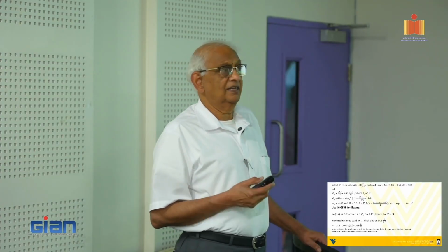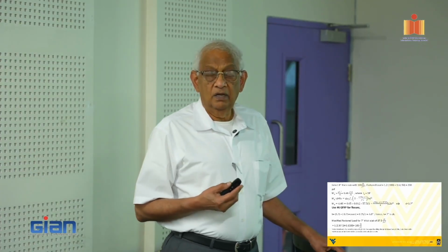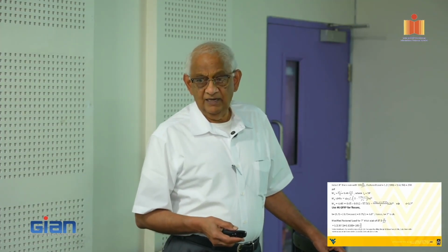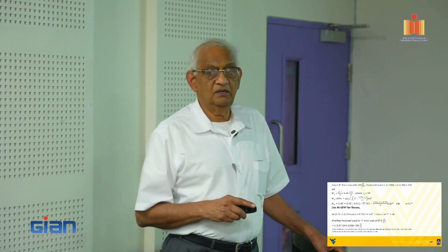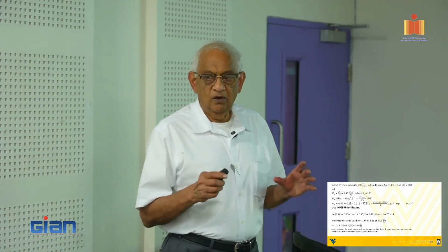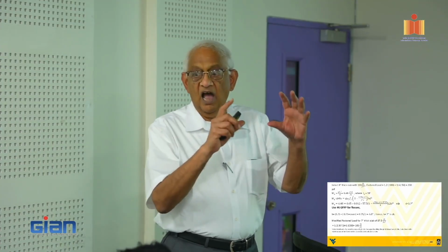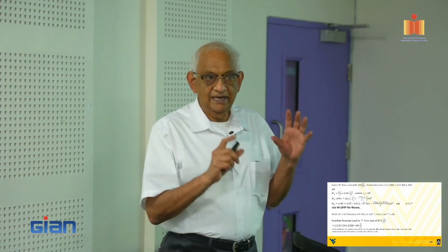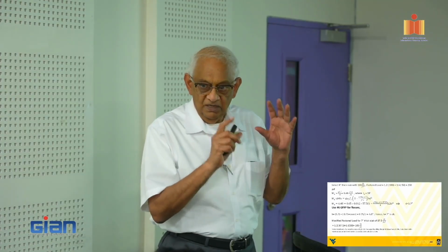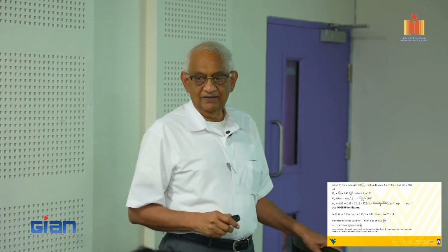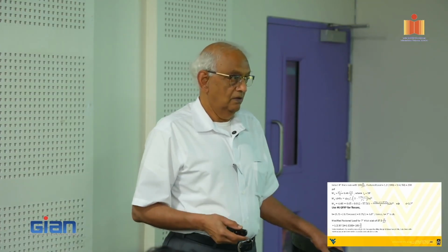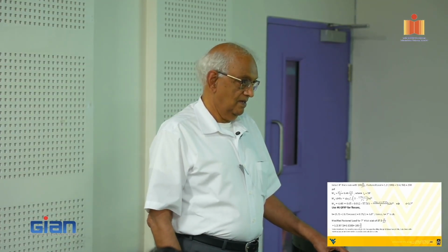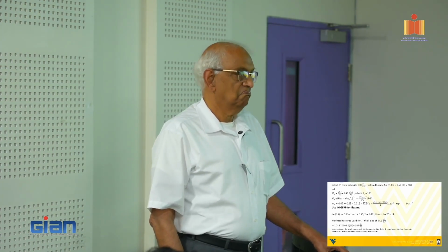So now suddenly we reduced a good amount of weight. You keep asking me about earthquake design. You know the first thing people worry about in earthquake design? How much can I reduce the top heaviness of any structure? The dead load, we want to minimize that. So this is an excellent example. In fact, in a building, the majority of the dead load comes from the slab. That's right. Optimize the thickness, you reduce the demand.